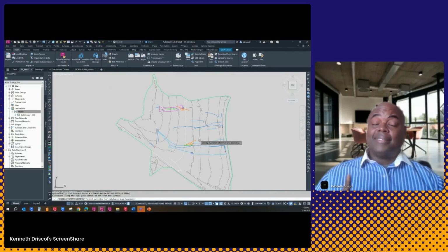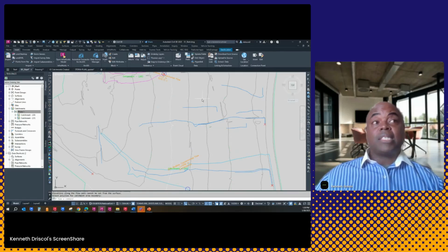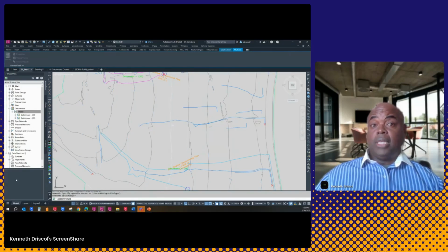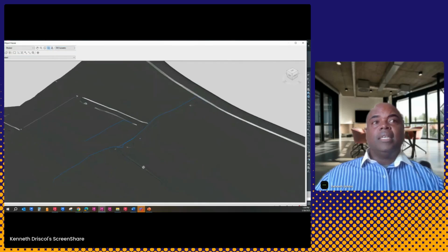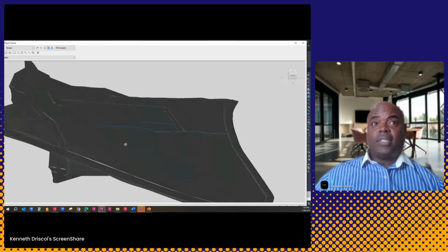One of the things that I made reference to is I like to use 3D polylines. And the reason is because if I select on my polylines and my surface, right click and go to object viewer. And let's just make sure this comes up. If I go in and look at this Southwest isometric, that hydraulic distance, and if it doesn't create a flow all the way through, there's a reason why it doesn't. And I like to see that in 3D. It just gives me a better view of what's going on in terms of my site.